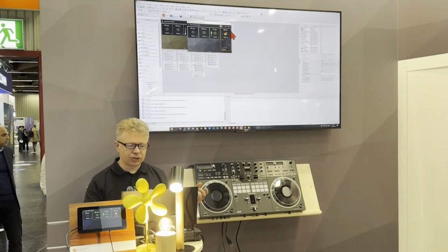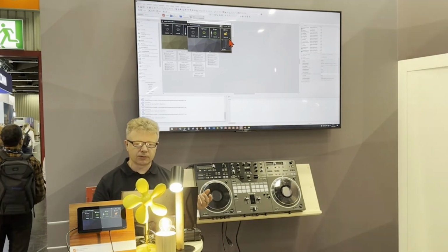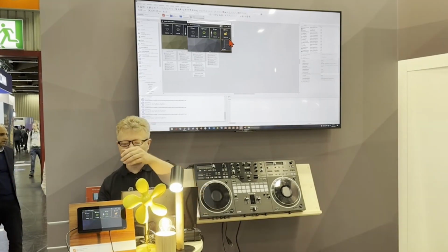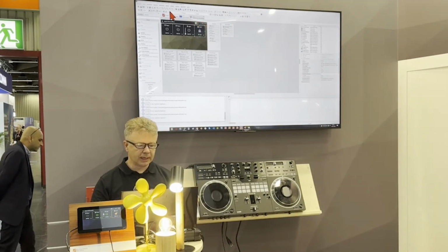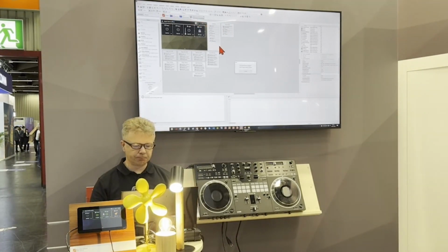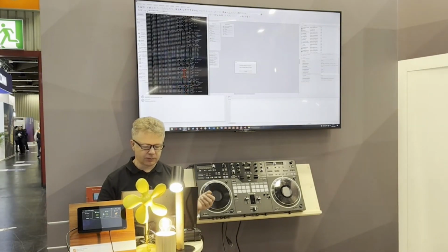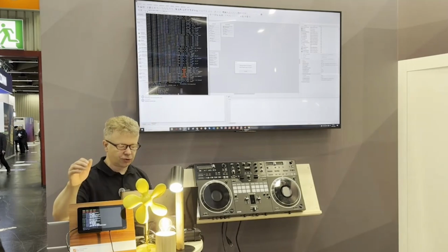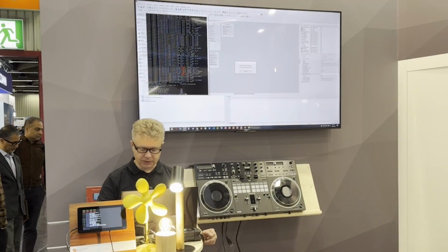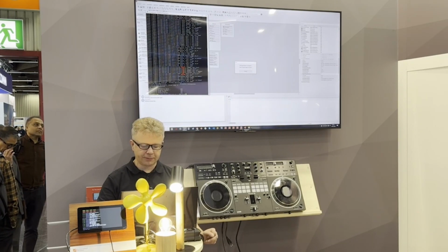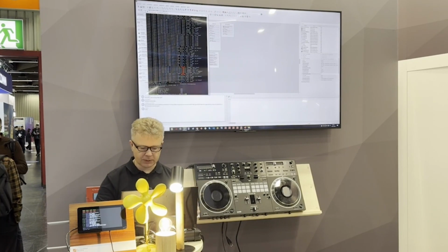And now the next stage: it's not just that you do all this on the prototyper. The same what you see here on the prototyper, you will immediately get also on the device as soon as you generate the code. That means now with this, I also generate the code for my Raspberry Pi. And as soon as code generation is done, I just connect it and let it rebuild. So I simply stop the application which is already running here. And as soon as the generation is done, I also will build the whole stuff again. Let's just wait. Code generation, it generates on a network device for the Raspberry Pi.